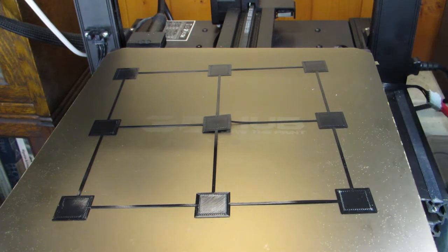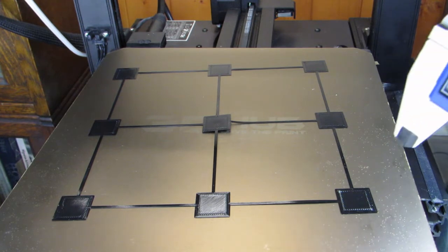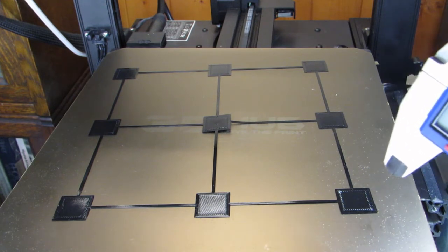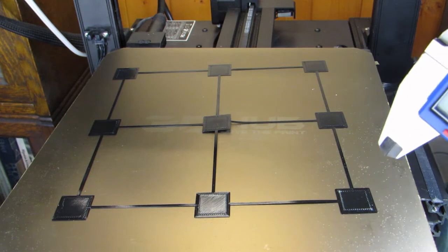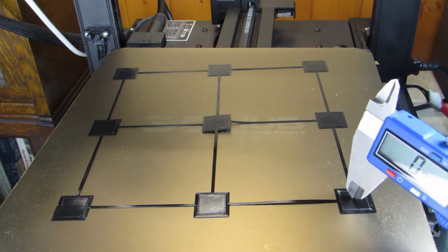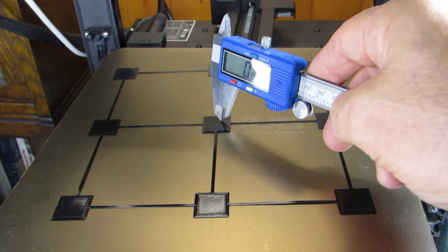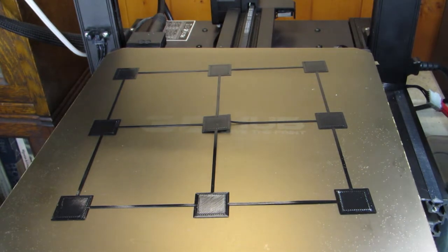When you're building things where the dimensions have to be absolutely critical, that argues you're going to still have to test and adjust things for your particular printer's performance to get to the dimensions you want. You can't just fire and forget. But the offset setting method that I've offered you here, I think, is vindicated by this pattern and the results we got.